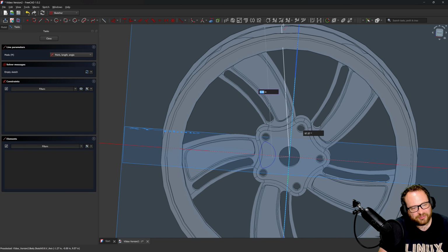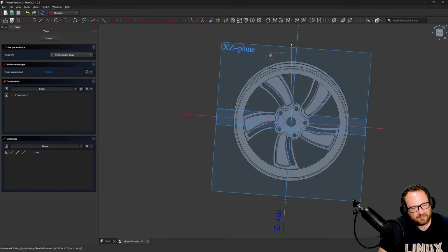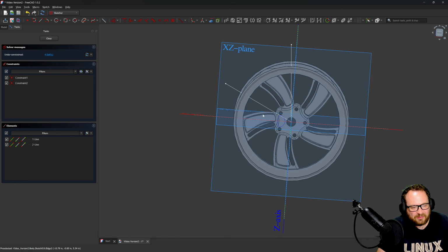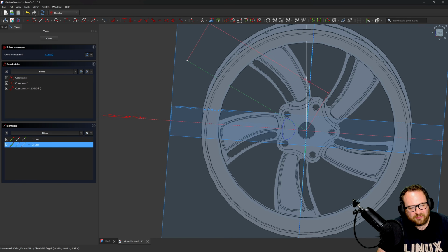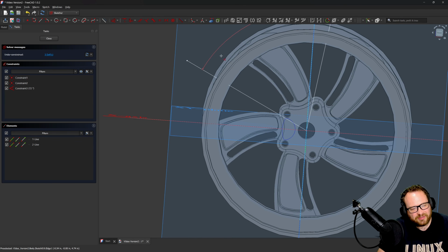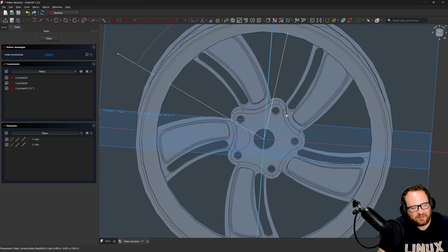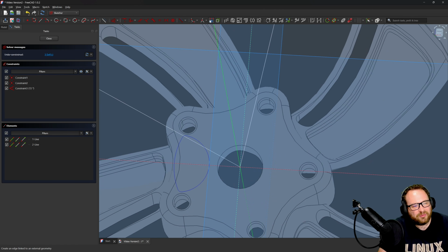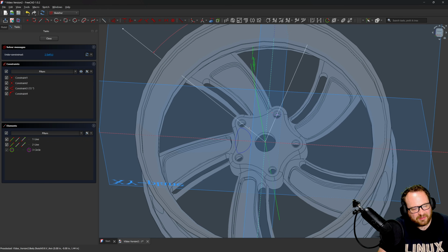right there in our origin, and I make another line, and I create, again, D for distance, or dimension. I make a line that's 72 degrees, and maybe I'll import this circle here, and I'll say C and get that right there.